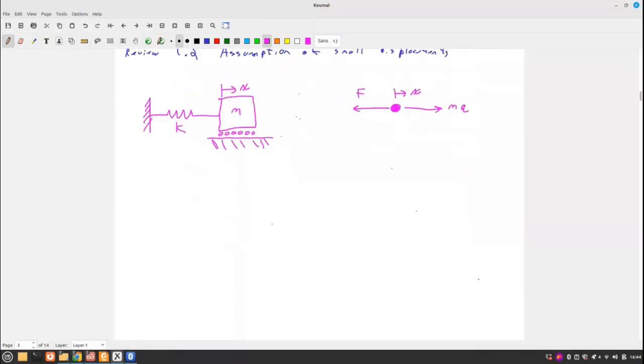All right, I also want to talk about linear springs. So in this course, all we do is linear, right? Everything is linear. And so we need to talk a bit about linear springs as a way of introducing the conceptual aspects of linearity. When we have a linear system, it doesn't matter how far things displace or what speeds they move at, everything is always going to be governed by the same set of equations. So a mass is linear. It doesn't matter how fast our mass is moving for our systems, it's always going to be the same mass.